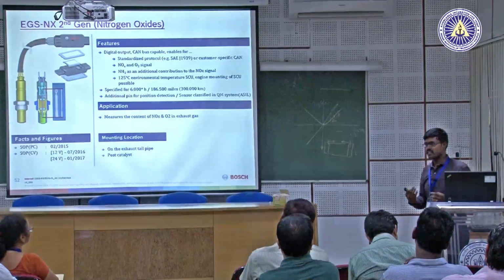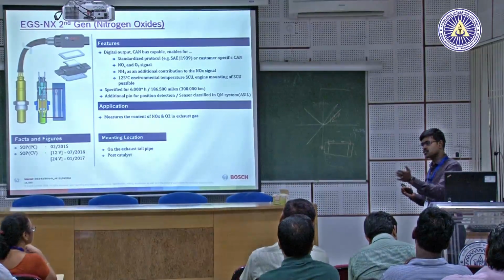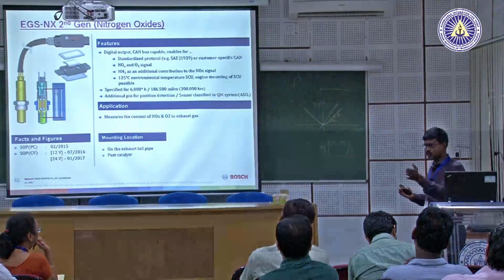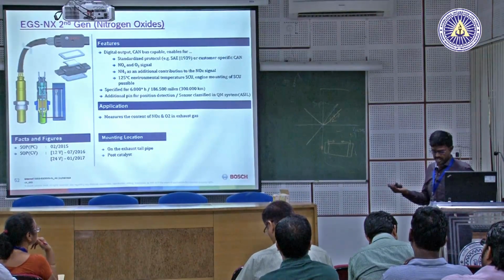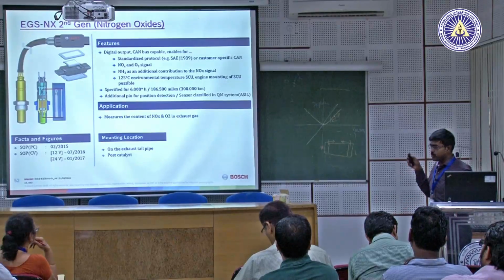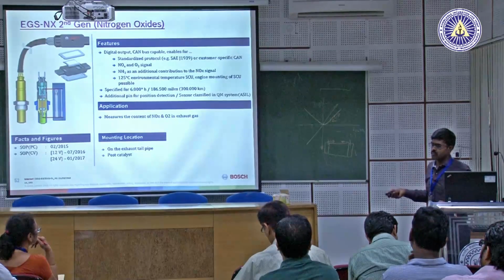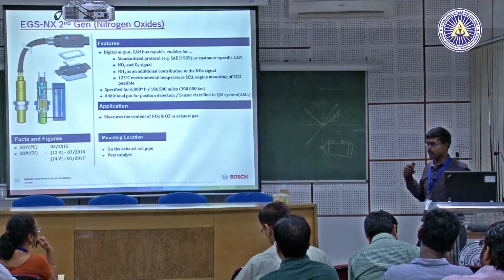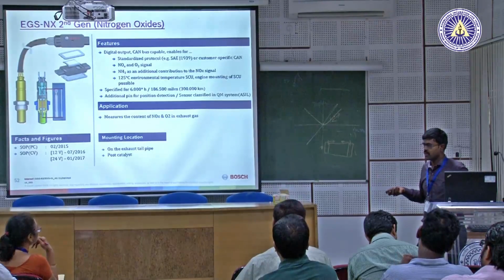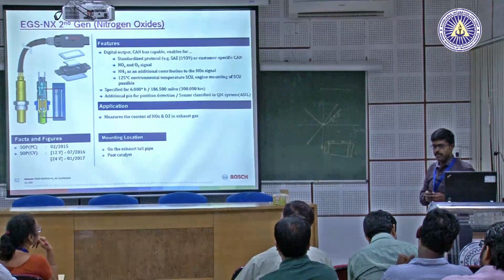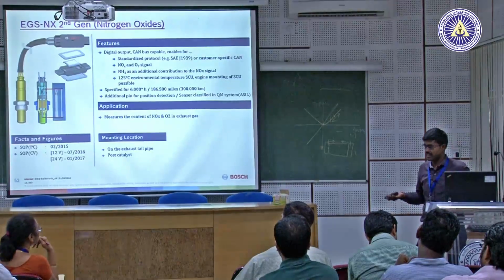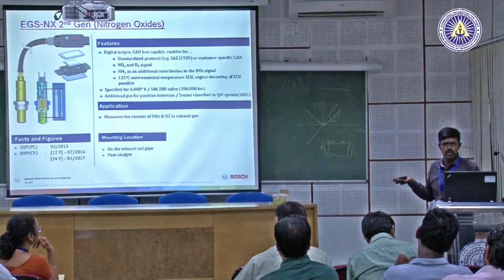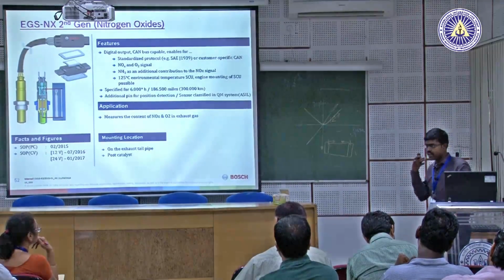You are reducing, meaning HC is converted to H2O and CO2, CO is converted to CO2 like that. Okay. As a byproduct of that SCR topic, because ammonia is NH3 again, N again reacts with O2, it becomes nitric oxide, N2O, NO2, NO, all these things are again harmful.